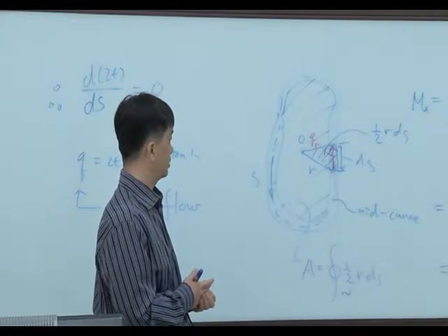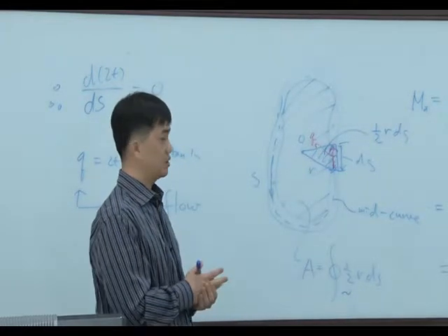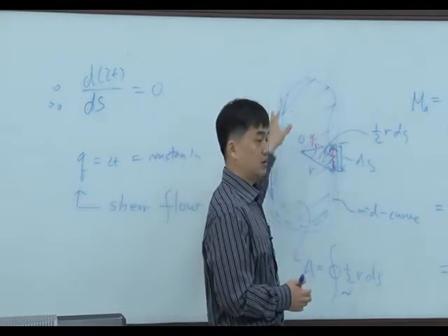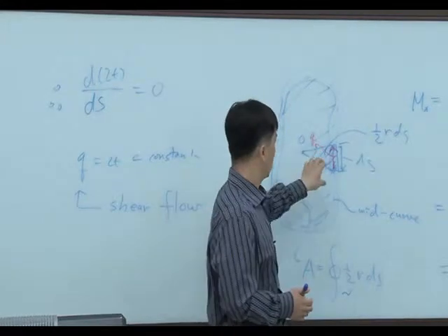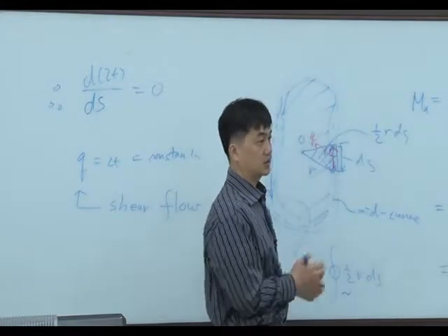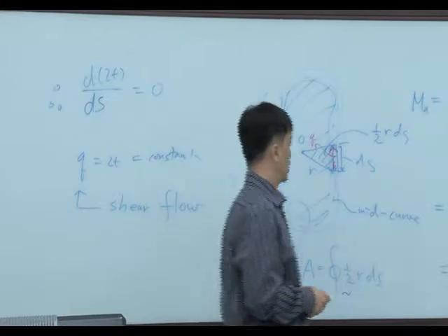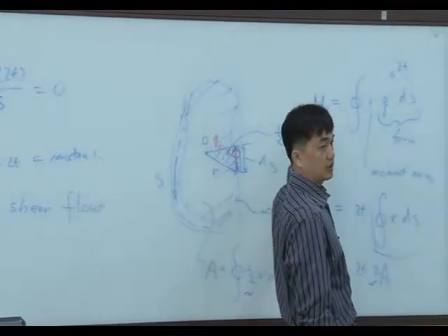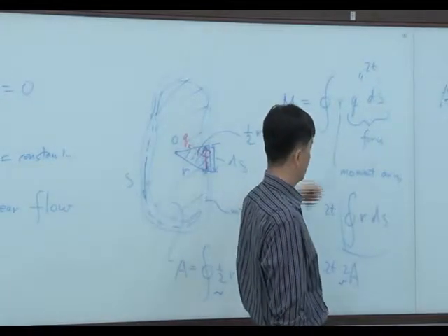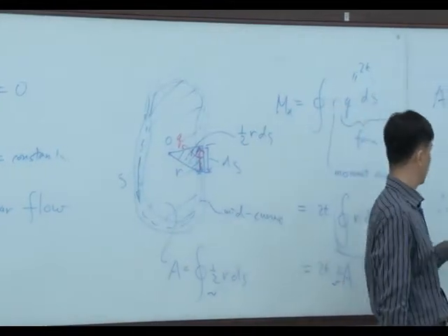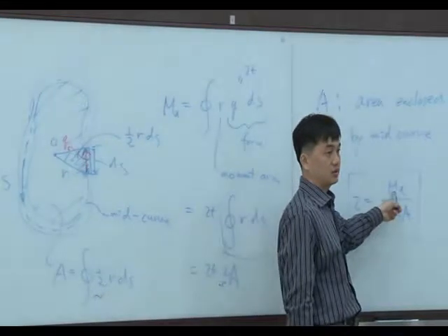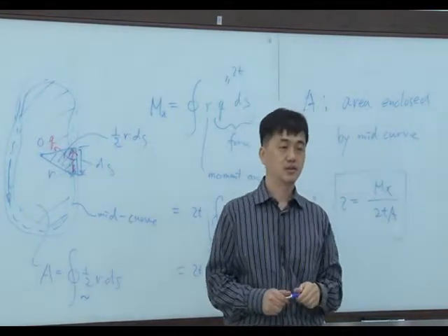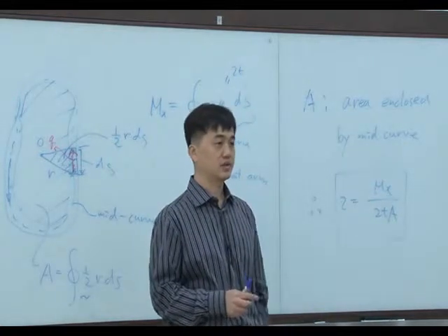And then, by integrating that shear flow along the mid curve, we can calculate the twisting moment, and then we get the relation between twisting moment and shear stress.